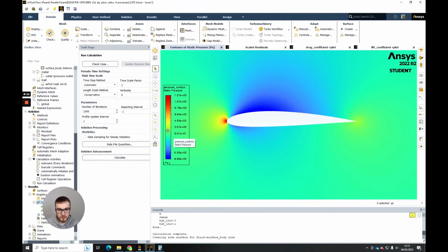Whereas below here, as you can see, the green contour represents a positive pressure. We should expect to see the force pushing the airfoil up below. So the way an airfoil works is we get a kind of a sucking force upwards and a pushing force below, and that causes a lift force. Now there are regions of negative pressure here, and that's because we have a 0-degree angle of attack.